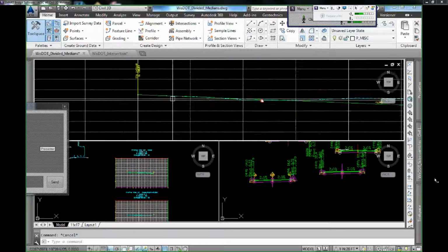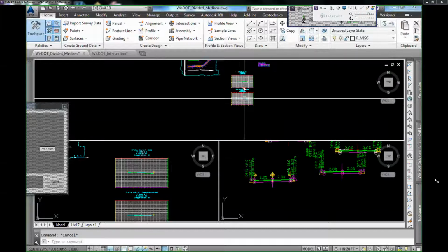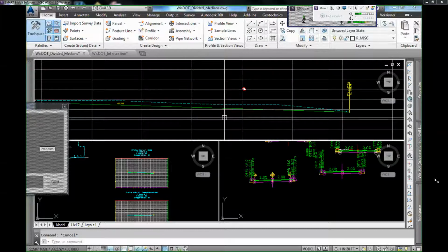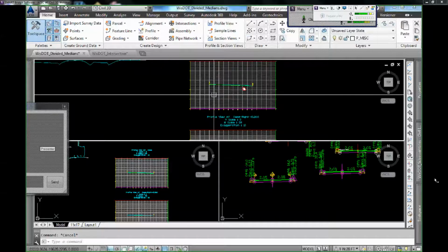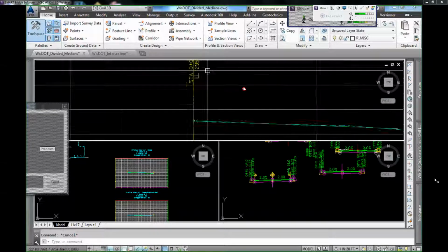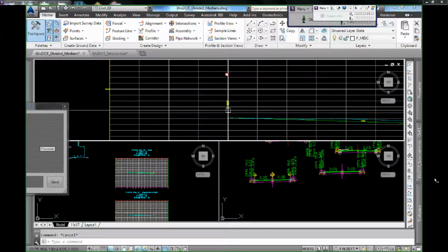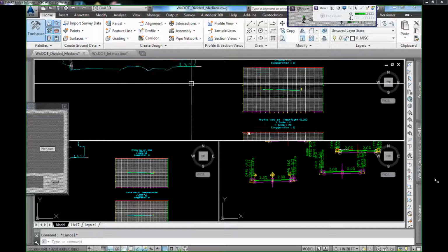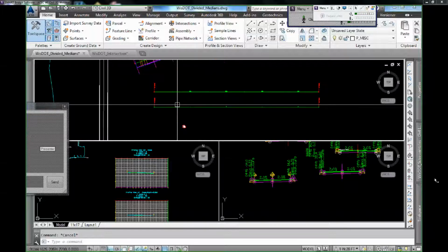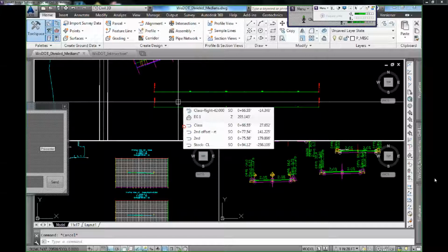Now, just for simplicity, I just did a straight line grade from start elevation to the end elevation on both of these, so nothing real special about this. So they are not going to match, at least I don't think they will. So my elevation starting point here is 95.54, and we got 95.45. So I'm 3/10 difference between right side and left side, and that's fine. That's one of the advantages to using this method, because again, you can control the right side and left side independently from each other if you want to.